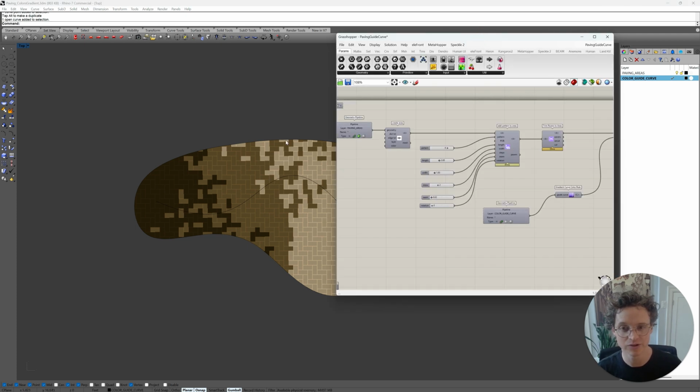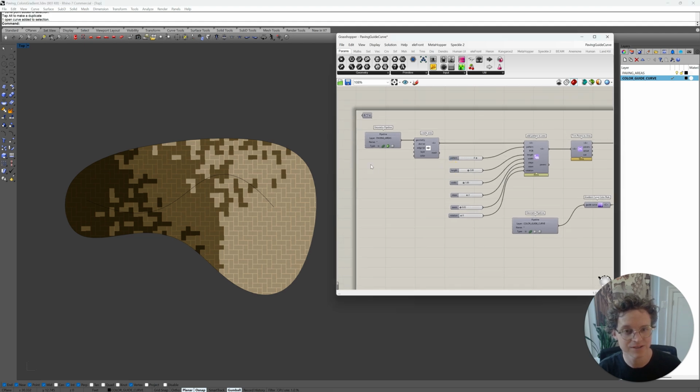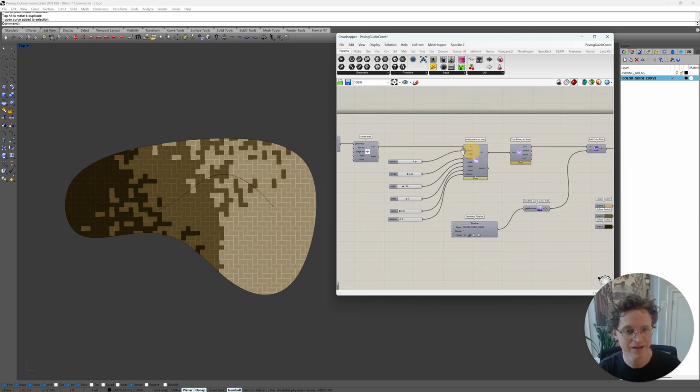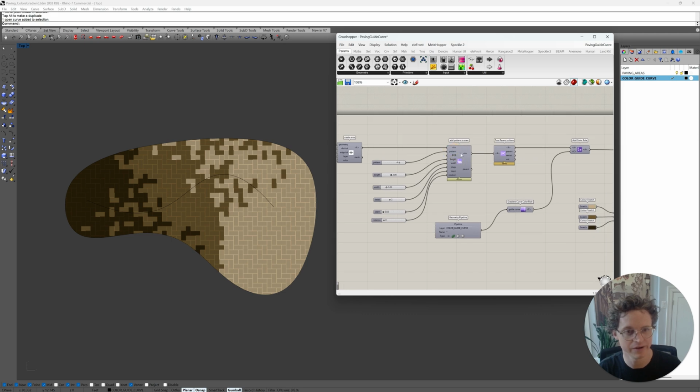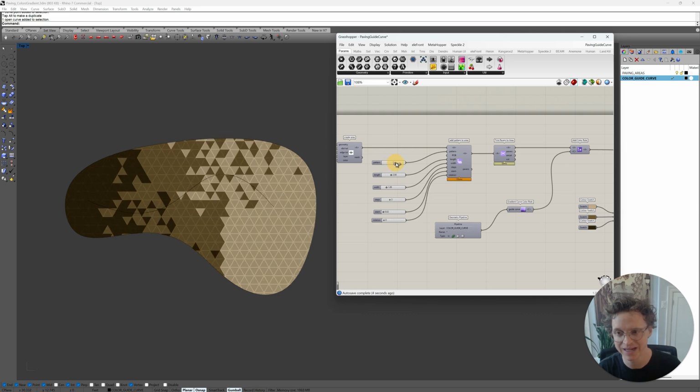So how does this plug into the Grasshopper script over here? We have our standard setup of our geometry pipeline bringing in our paving area as a curve or a surface or Brep to create our area. And we're adding the pattern to the area so we can change that pattern as much as we want. And that gradient of colors is still maintained.